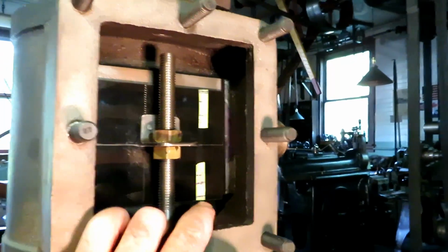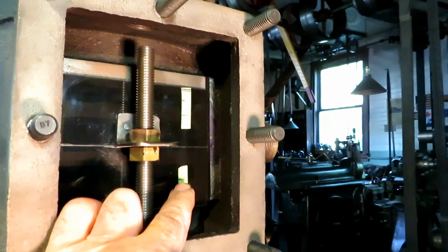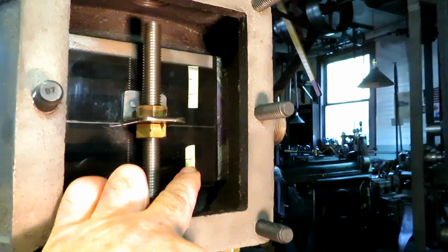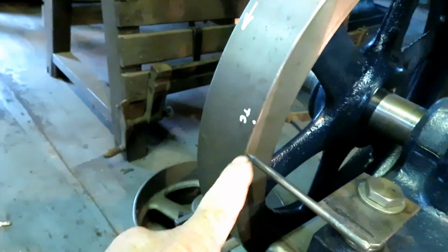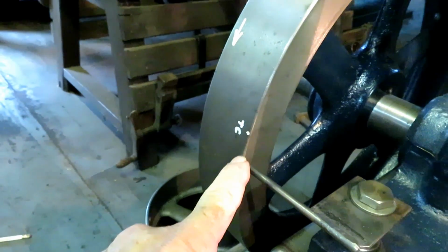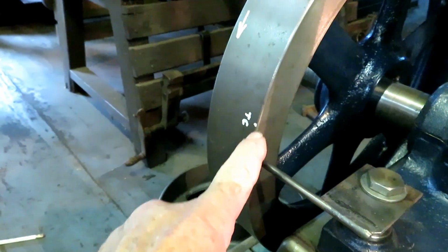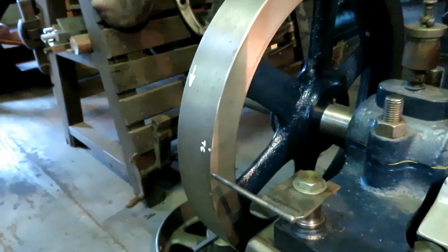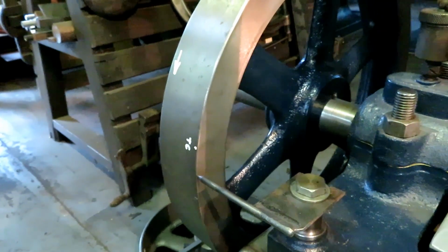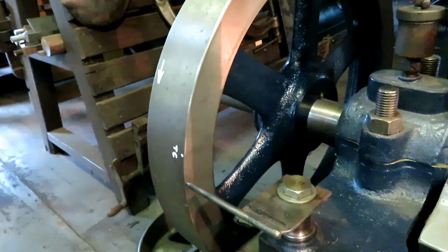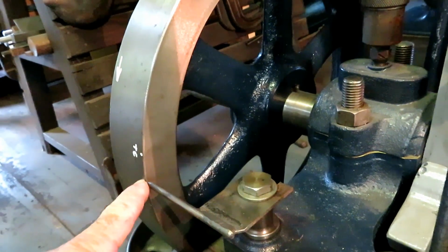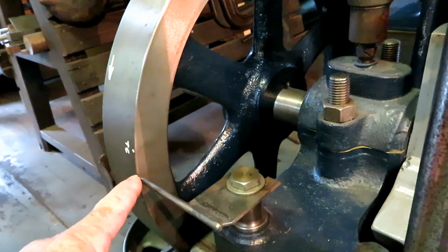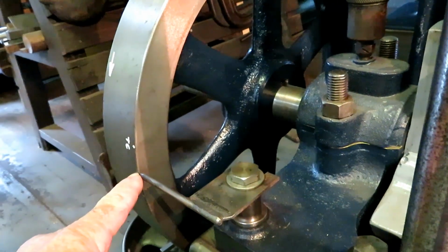Now I've done the same thing for the bottom half of the cylinder, and I've marked the release point. And when I bring the release point back down to close the exhaust off, and come over here and you look, there's only this much cushion on the upward end of the stroke. And that's because of rod angularity. It's really the only dimension in the whole valve layout that is thrown off that much because of rod angularity, and that's because it's an event that happens fairly close to top dead center. So that's where rod angularity makes the biggest amount of difference.